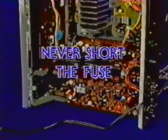Never short the fuse and apply power to the supply, hoping to identify the defective component. This technique generally produces more bad components than it identifies.